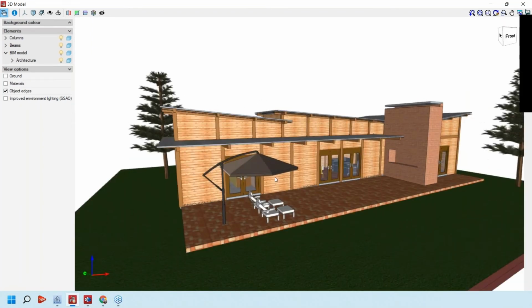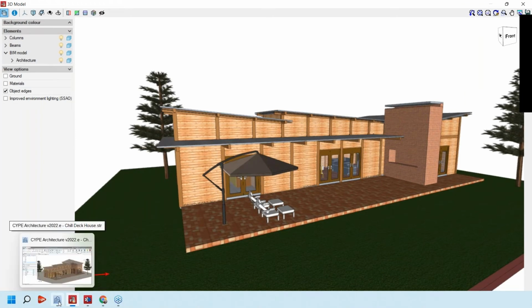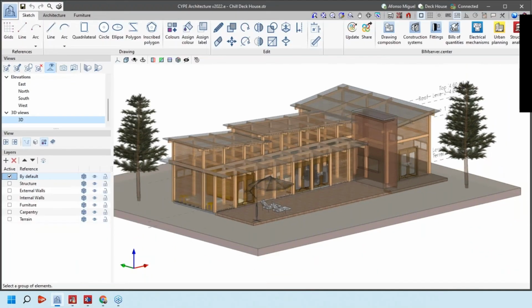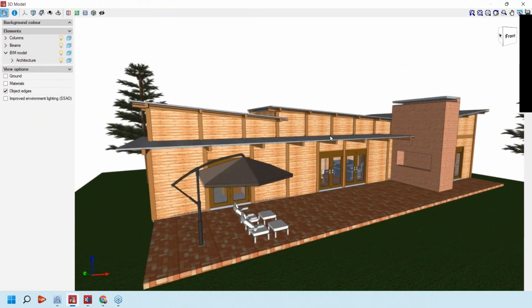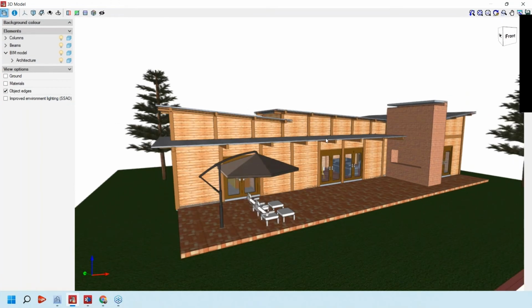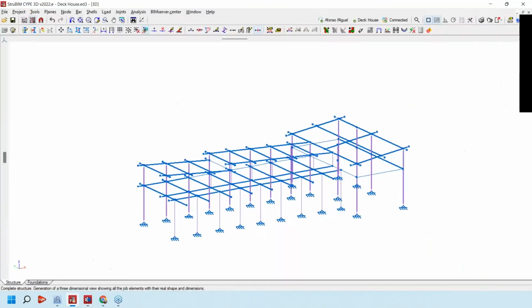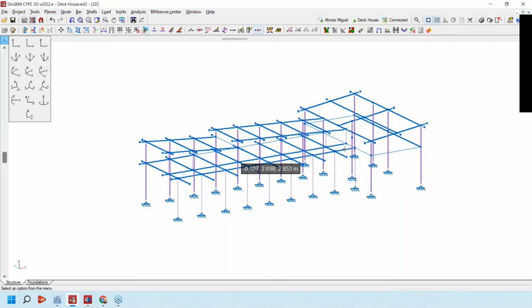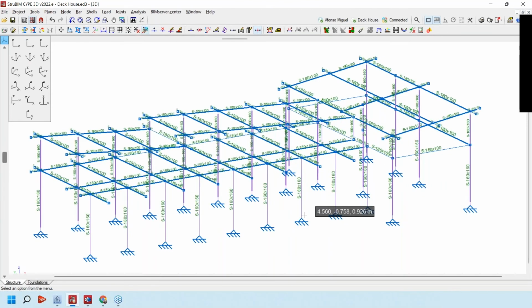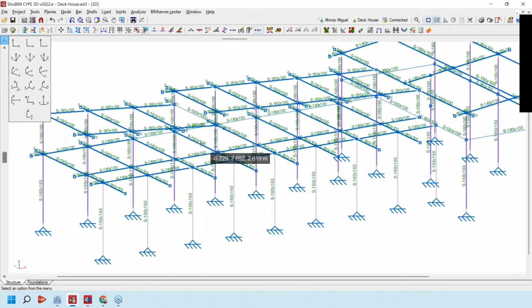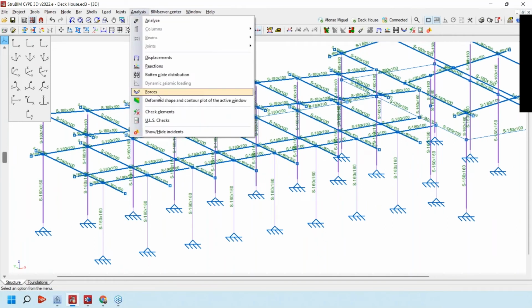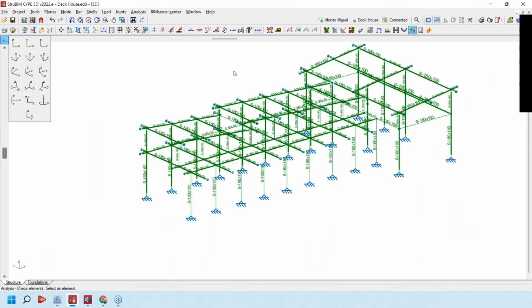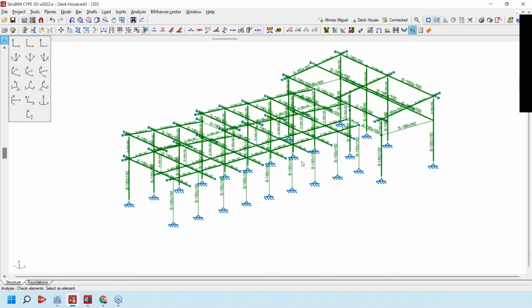That's very useful. Two different programs, two different purposes. One could be used, for example, by the architect, another one by the structural engineer, and we can connect the information from one software to another, okay? Here, during the calculation, during the design in this software, you can see that the analytical model was developed considering different types of conditions with different sections. And we can, for example, see the elements here. The elements are in green state. It means that everything is checked according to a specific code that was selected.